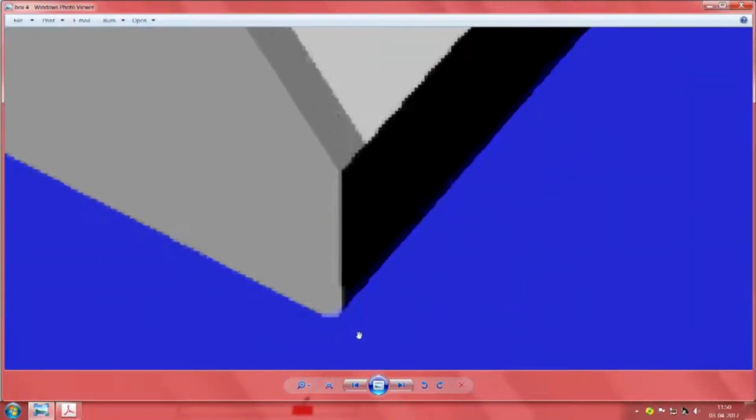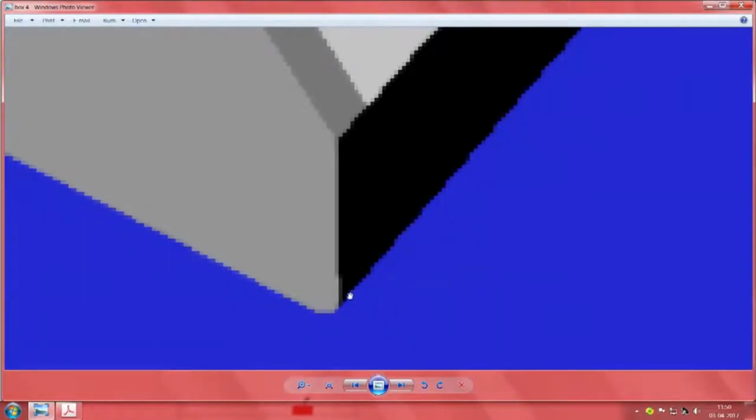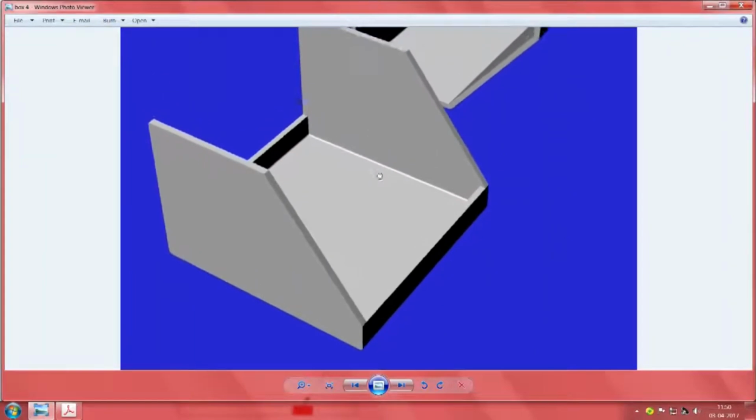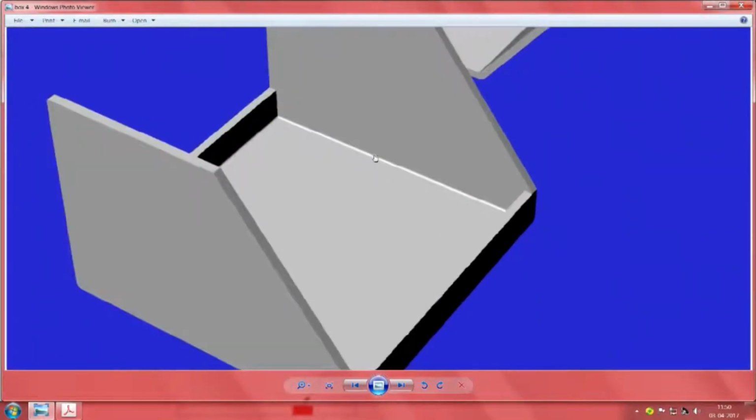demonstration downstairs, have you seen here a radius is there that involves two radiuses. One is an internal radius of the tool when we try to do the bending on the bending press or the brake, and then the sheet thickness itself. So, typically depending on the constraints and depending on the behavior of the material, at least 0.5 millimeter internal radius is preferred.